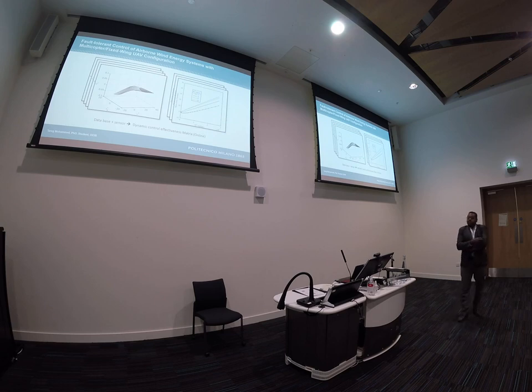Then we also tried to build a good model for the quadrotor. The thrust is affected by the apparent airspeed of the kite, since we are flying at very high speed. So we built a solver to build a table that matches the RPM of the VTOL system rotors at different relative airspeeds, and then we include all this data in the simulator. So we have the simulator for the VTOL system, for the tether, and for the kite, or the glider, itself.